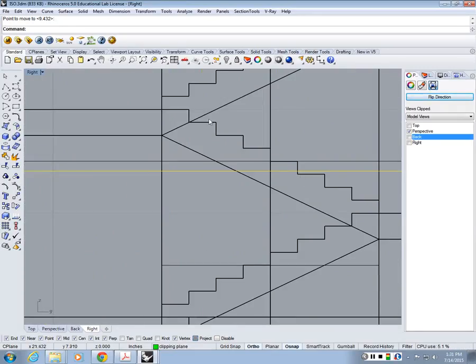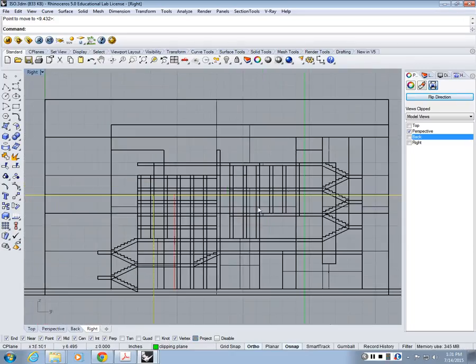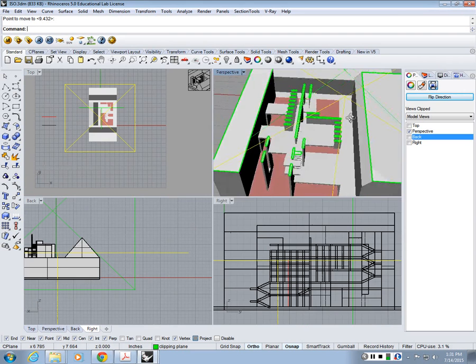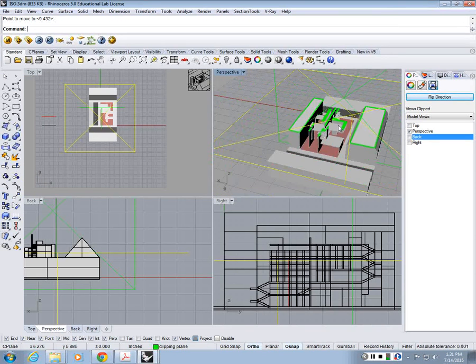So what I'm going to do is draft these with dashed lines, the ones that are going to be behind my view. And the ones that I'm seeing, I will be drafting them with lines as well. And I tried to cut through a level where I could see most of the detail, the columns of the plan. And I'm cutting through these buildings as well somehow, so I will have to give them thicker line weights as well. So again, similar process.